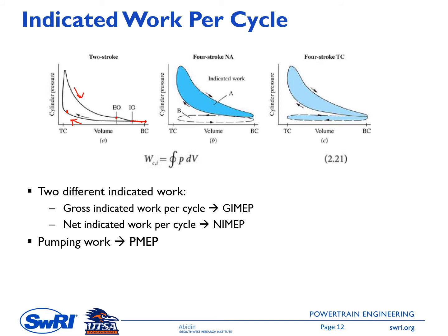The feature in the middle here is the PV diagram for the four-stroke naturally aspirated engine. We will study this in more detail, about this naturally aspirated engine as well as the turbocharged engine, in chapters 6 and 7, I believe. Naturally aspirated means that the engine doesn't have a turbocharger, and the fresh air induction to the engine is mainly due to the pressure difference between the intake manifold and the cylinder pressure.